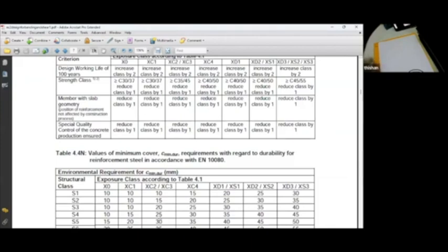So that is something extra. So it's much easier to just keep 35 millimeter cover in the slabs as well. But if you want to have a really thin slab, you want to optimize it, then you need 25 millimeter cover for the slabs, and then you have to buy a cover meter, and when you are doing the concrete, do it carefully so that 25 millimeter cover can be verified and assured. So that is the situation. But if you are doing, say, a 150 millimeter slab, keeping 35 millimeter cover will assure a building that will not have any problem over a very long period.